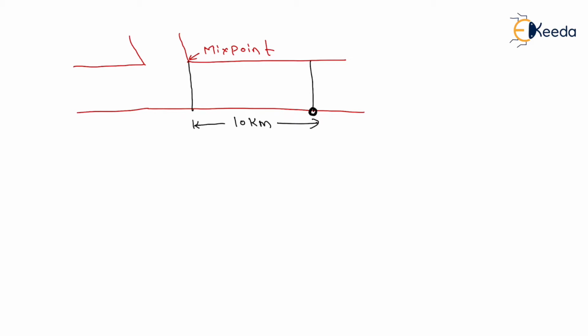Now the total discharge is given as 8.5 meter cube per second. And the BOD of the mixture at the mixing point is given as 44.7 milligram per liter. Clear? Now if the 5 days BOD of the mixture is given, can we calculate the ultimate BOD from this?